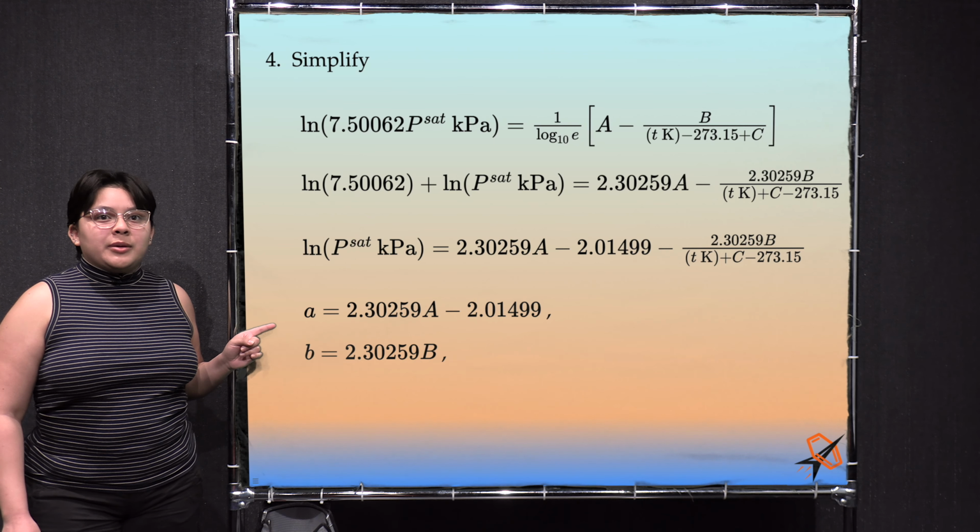You should now be able to convert any equation with dimensions into any other set of units. The takeaways. To convert an equation, as opposed to a value or a variable, from one set of units to another set of units, do the following steps. 1. Start with the variables in the target units, the ones you want to end up with. 2. Convert your target unit variables to the original units with dimensional equations and/or temperature conversions. Don't forget the difference between temperatures and temperature intervals. They get converted differently. 3. Plug the converted variables into the original equations. 4. Do the arithmetic and algebraic simplifications.